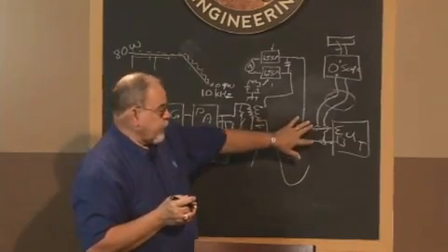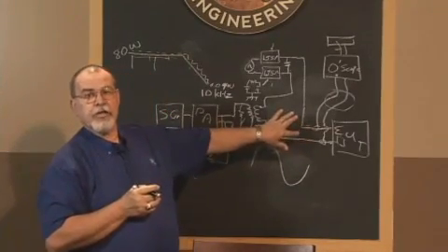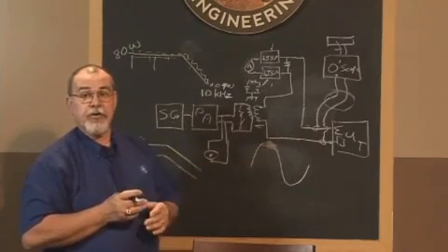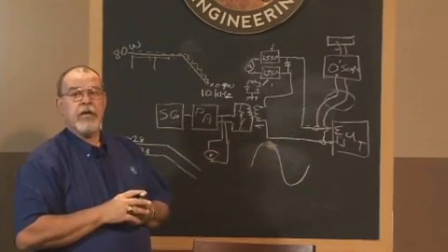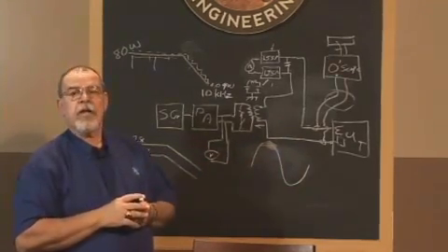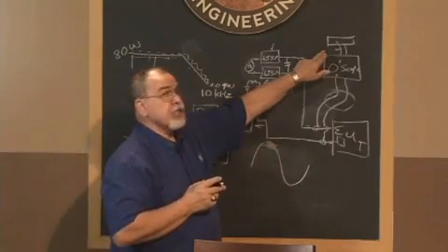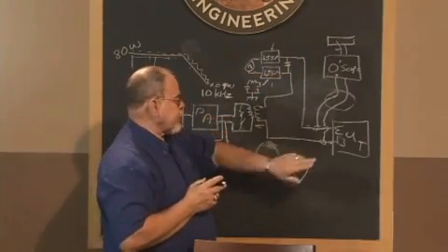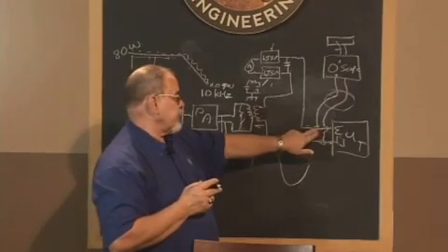If this is a floating neutral with 480 volts, you're going to get between there and the actual ground, and your body will be the conductor. It is a pretty severe shock. So remember, we need to isolate unless we're absolutely sure this is a grounded neutral.